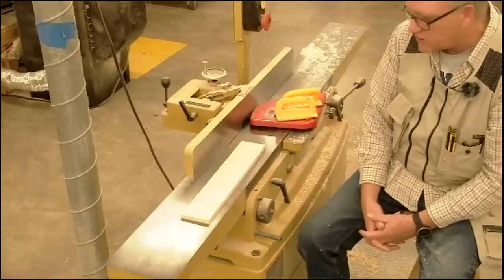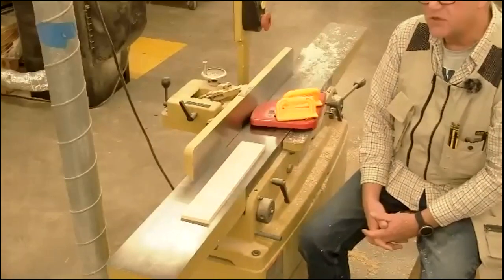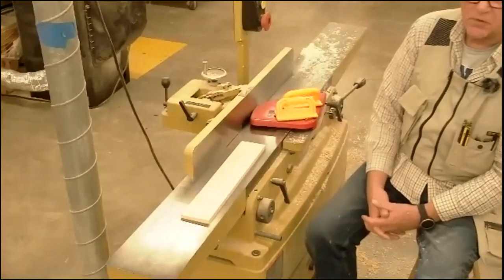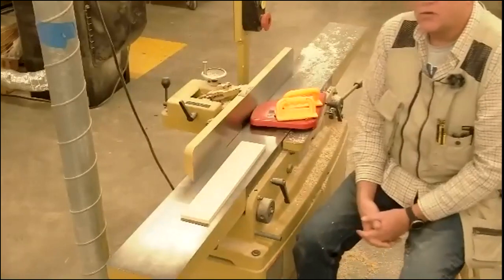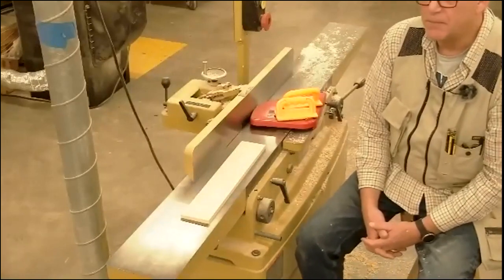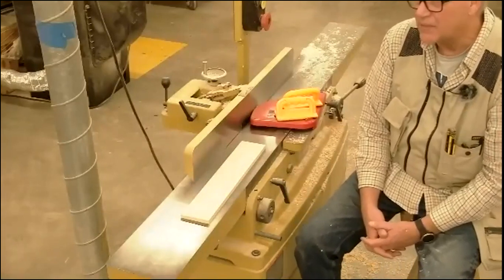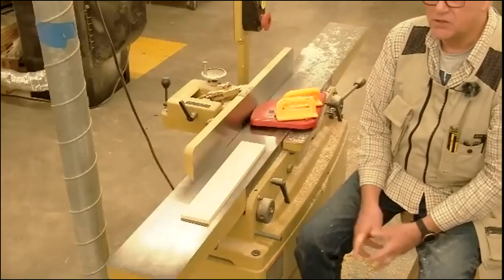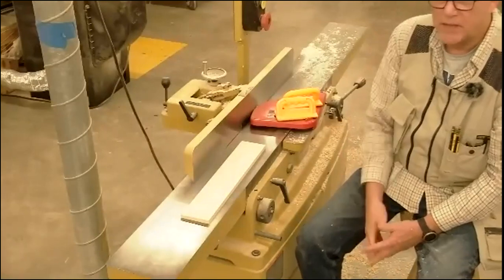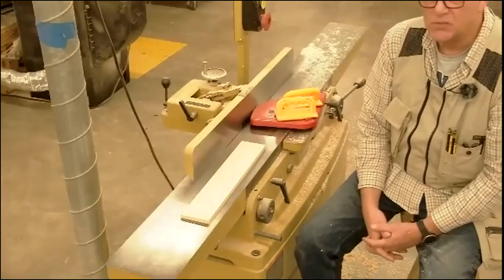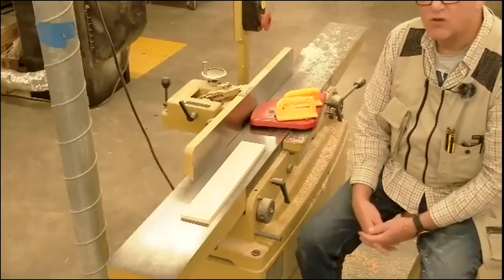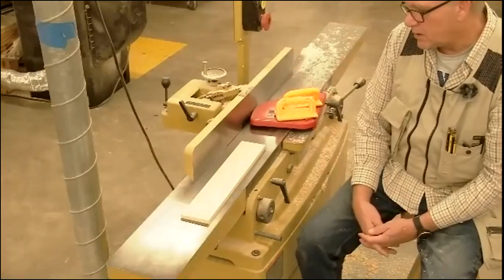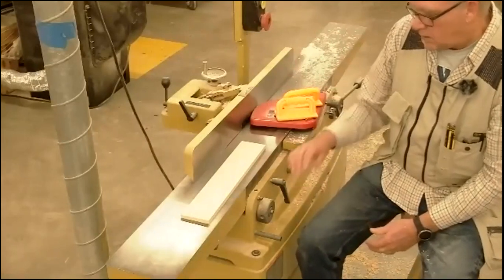That's the first thing you're going to do to a board after you've done a couple other things, right? You guys have to remember that the first thing you'll do with a piece of raw wood is you'll put it onto a table, you'll draw your parts to rough dimensions that you expect to get out of that board, then you'll show it to me, I'll check it off, then you'll likely go over to the panel saw and cut it into more manageable pieces. You don't want to take a 12-foot board and try to joint the face of a 12-foot board on this jointer. Then we go to the planer.